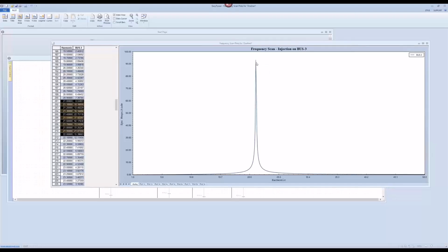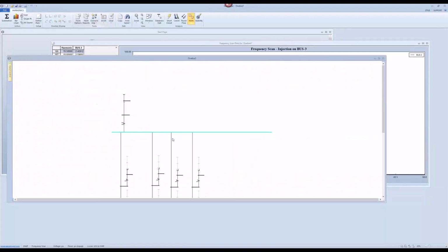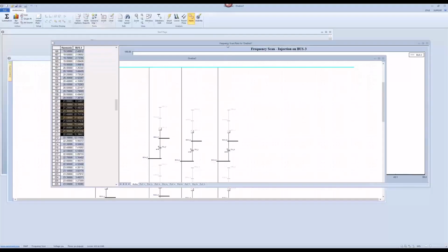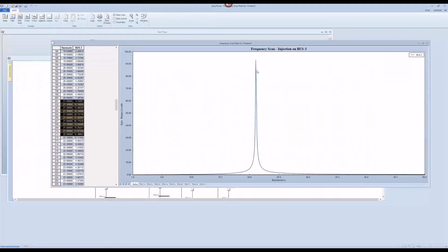here. And we know that the spike is caused by what? It's caused by the resistance or capacitance provided by the cable, because we have a collector cable system, right? So in this case, we know that any capacitance between the phase and the ground would cause a resonance point. And then we already have the resonance point introduced by the capacitance of all the cables I have.